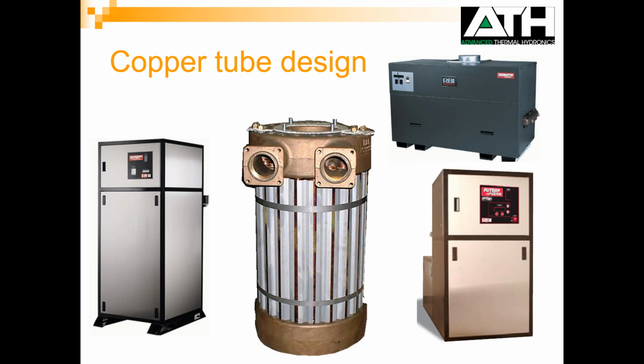Now, one of the things about a copper fin tube boiler, all of the heat transfer is really done through a small copper fin. And on the copper fin, you typically only have about 2 to 3 gallons worth of water in a 2 million BTU per hour boiler. So what does that mean? It means you have to have a constant flow of water through the boiler at all times. You can't have only 3 gallons worth of water and 1 to 2 million BTUs worth of burner on the other side, because if you stop the water flow through the boiler, that water would turn into steam relatively quickly.